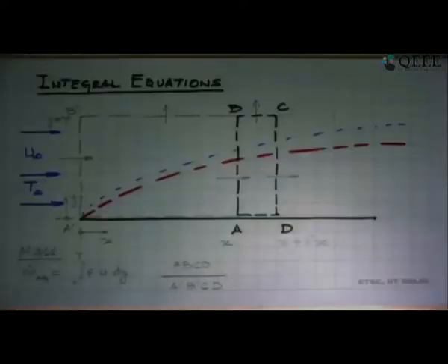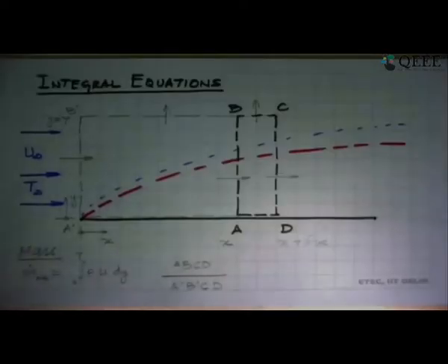to looking at the integral equations of the boundary layer. This is different from what we learned previously, which were the differential equations of the boundary layer. There we took an element, found out what all the mass, momentum and energy inflows and outflows are, what the forces acting on it are, and then using the second law of motion, the first law of thermodynamics and the conservation of mass, we wrote the conservation equations. Those are good because when you do a computational solution of a problem, that is what you do. When you go back to the analytical equation, you again break it up into discrete points and then solve the differential equation using various numerical techniques. So that is important for all types of computational issues.